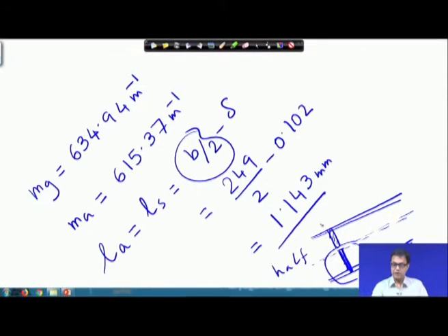In fact, for a symmetric configuration like a two stream exchanger, half of the fin is really attached to the upper plate and the other half to the lower plate side. We will get into this in detail when we talk about the multi-stream plate fin heat exchanger.